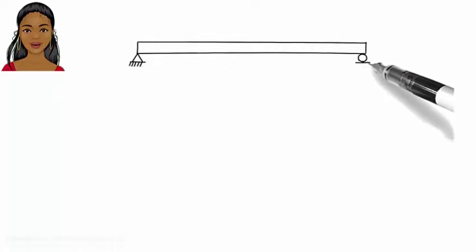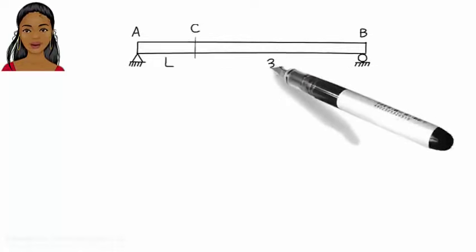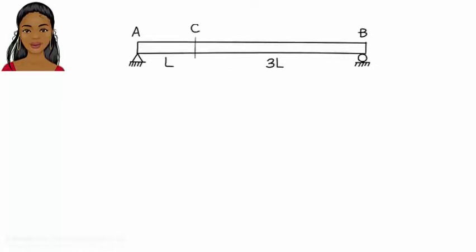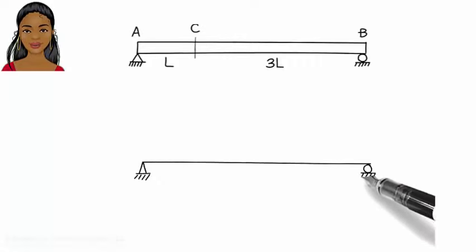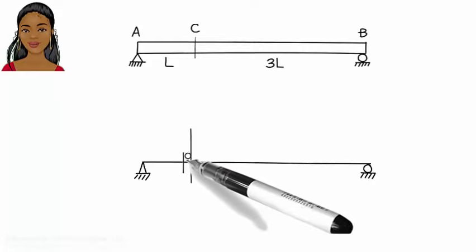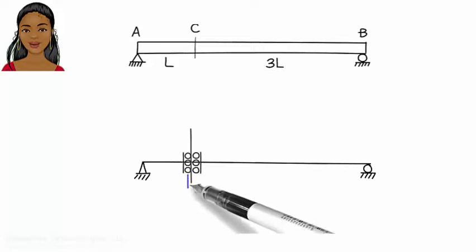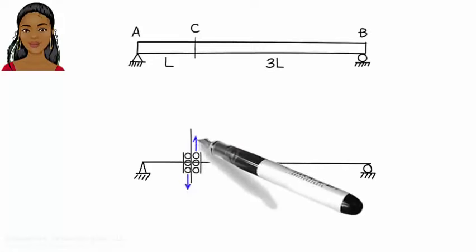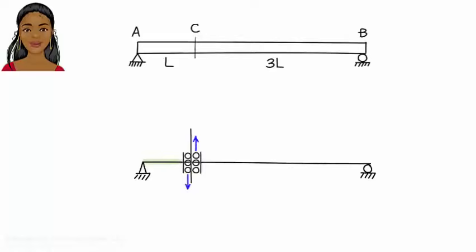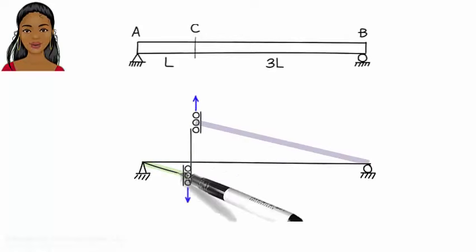All right, we now know a thing or two about drawing shear influence lines qualitatively. Now let's talk about determining shear magnitude in such influence lines. Here is a simply supported beam. Say we want to draw the influence line for shear at C. A pair of rollers. A pair of shear forces. The deformed shape. Here is the influence line.